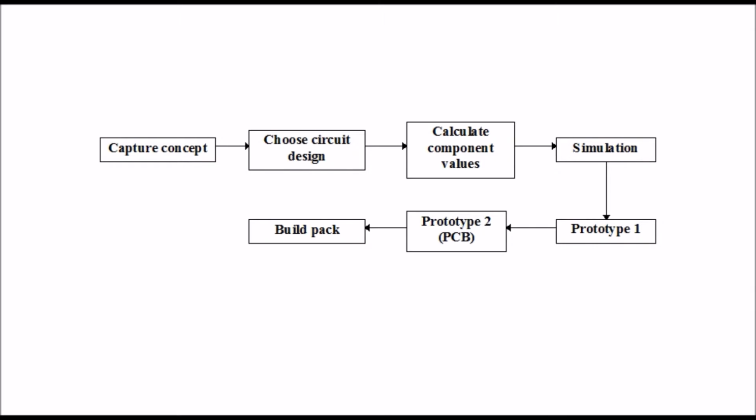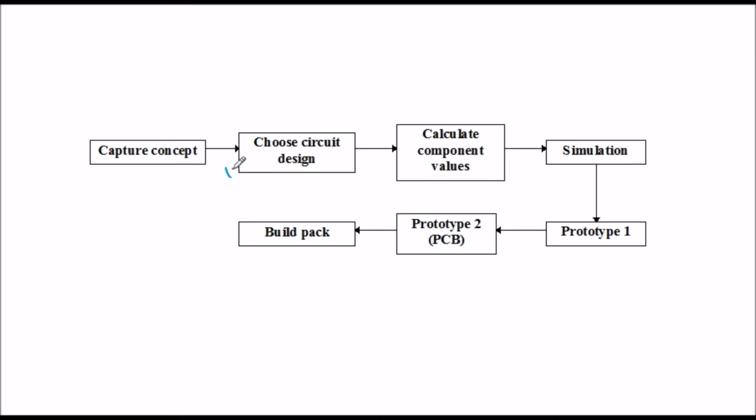There are often several choices, perhaps using different types of electronic device or different topologies of circuit. We'll see some of these later in the course. Some of the important points a designer will consider at this stage are the complexity of the different options, the power supply requirements of the system, the cost, the required noise performance of the circuit, the required specification, like the gain of any amplifiers for example, the availability of components, and other issues, for example special performance requirements.